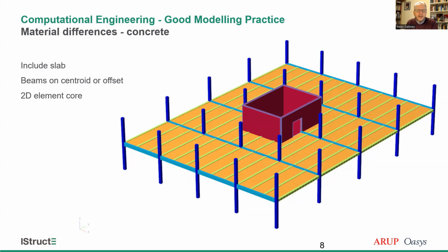Sometimes people have, especially in the past, used 1D elements for the aspects of the core, a column on each wall face. That's not done much these days. Before we had 2D elements commonly used, that was the way forward. These days, I don't think I'd bother. I'll go straight for 2D elements and then use assemblies or similar to collate the forces together.